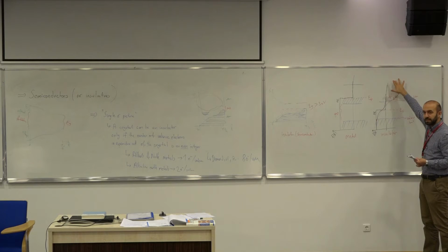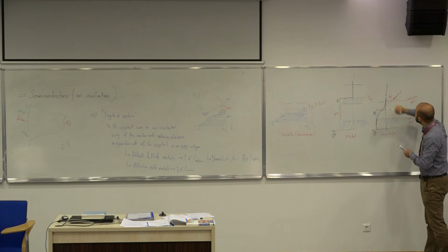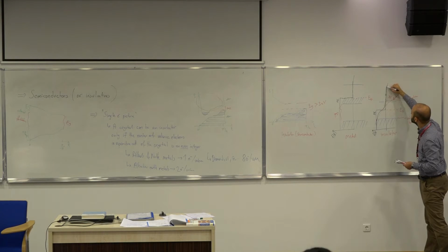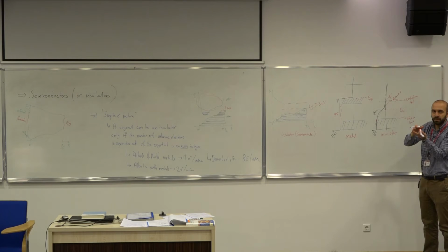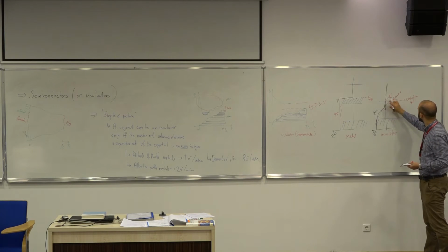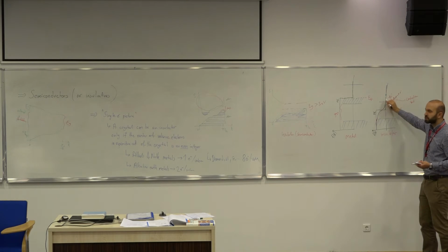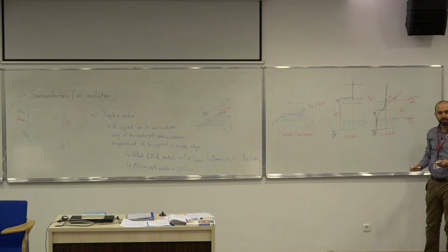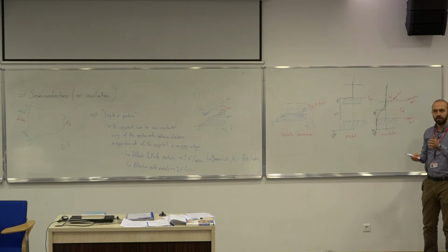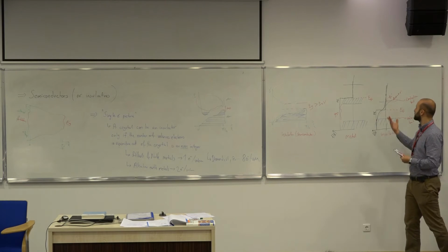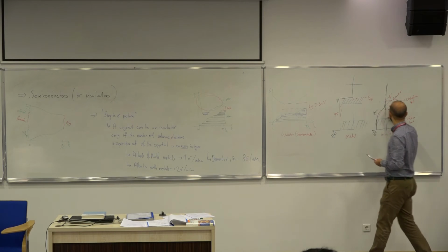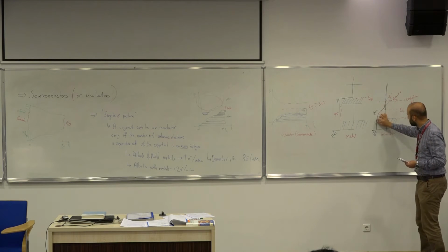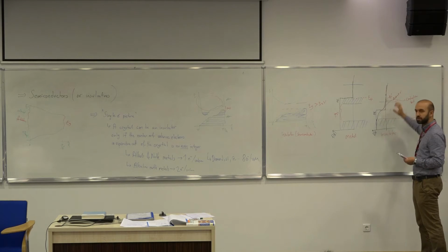Okay? Now, it should become more clear why we roughly say 3 electron volts for the Eg. As you keep increasing this gap, this tail will exponentially decrease. So the smaller gap you have, at finite temperatures, the more probability you have for your electrons to be in the conduction band. So this sort of marks the distinction between an insulator and a semiconductor. For instance, if you consider a 1 electron volt energy gap, then at finite temperature there will be a lot of absence of electrons, a lot of electrons here.